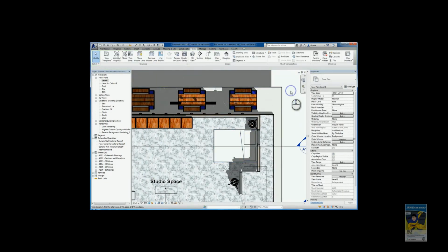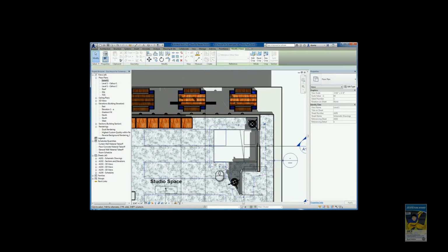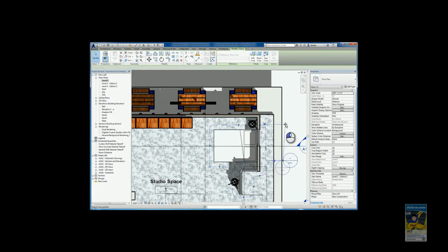The second method is callout where it is sketch based. Everything goes very light and gray, and now it's asking you to draw the magenta lines that represent the outside edges of the custom shape of the callout. For example, say something like this. When you're finished, hit the green check mark. That sketch will be created. This annotation will be created.